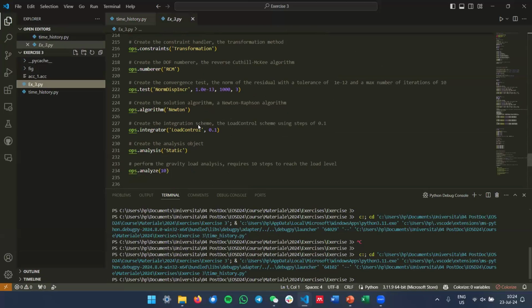Which type of problem? Maybe we cannot hear you properly. Yeah, sorry, can you hear me better now? Yeah, so we apply the loads for the beams in a structure using LE load. And then we perform the dynamic analysis. But if I want to account for large displacements, then I should use co-rotation geometrical transformation for the beams. But co-rotation doesn't work with LE loads. So how to tackle this problem?